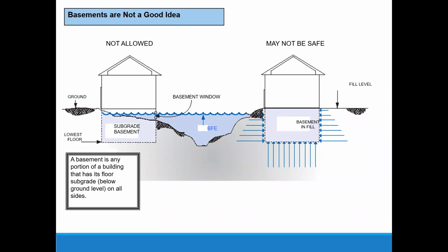And even basements close to the floodplain that are technically allowed are still not a good idea, and so we discourage that as much as we can. We've been talking about, whenever we see a plan like that that's close to the floodplain, taking a closer look at the data and seeing if we have something updated that might better inform construction close to those areas. So just something to think about. If you do come across a plan like that, we might have more detailed data that could help better inform them, and definitely recommend against putting a basement anywhere near the floodplain or in the 500-year floodplain.